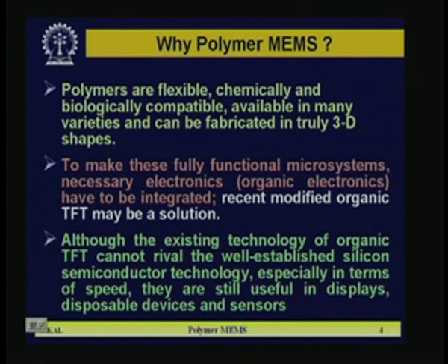A recent modified organic TFT may be a solution. Organic TFT has already come into the picture. TFT is thin film transistor, and that has helped a lot. Price has gone down drastically. But one point is certain, that the existing technology of organic thin film transistor cannot rival the well established silicon semiconductor technology, especially in terms of speed. In case of silicon devices, the speed you achieve is not possible in case of polymer devices,